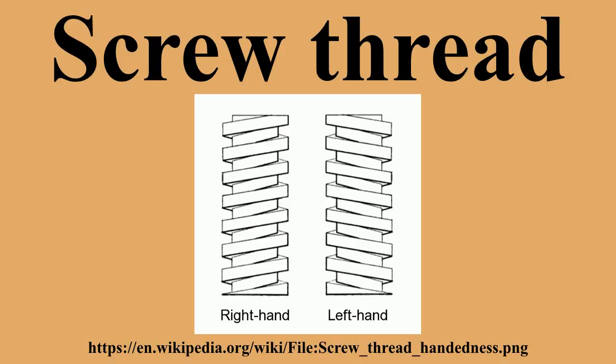The result is that tapered wear is reduced, the likelihood of breakage is lessened, and higher cutting speeds can often be employed. Truncation is achieved by using a slightly larger tap drill in the case of female threads, or by slightly reducing the diameter of the threaded area of the workpiece in the case of male threads, the latter effectively reducing the thread's major diameter.